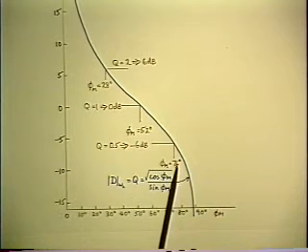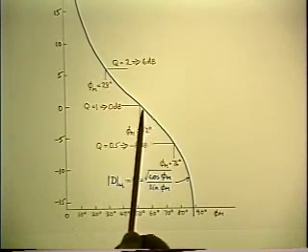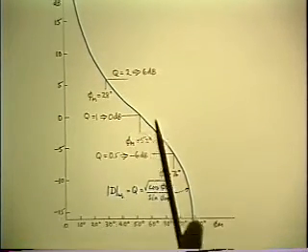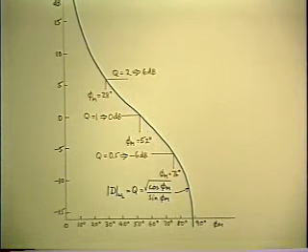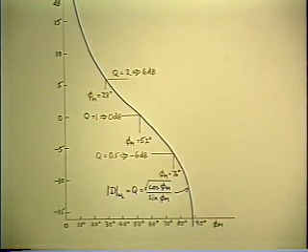So this is a very useful graph, especially if you remember this critical point. Q of 1 requires a phase margin of 52 degrees, and I would tend to translate that into something to remember, that you never want to let your phase margin get less than 52 degrees. Worst case. Not nominal, worst case. Now that may be tough to do. That doesn't do anything to invalidate this. Yeah, it's tough. You've got to live with it.